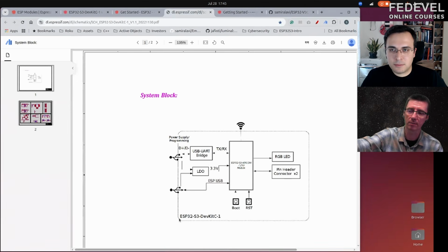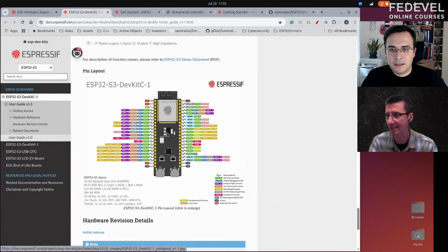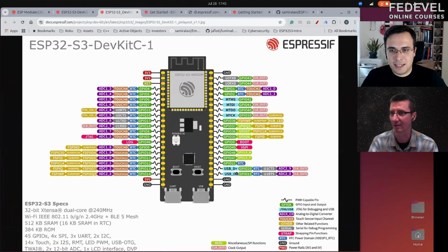This is nice. I use the picture a lot actually, especially for example, if I'm looking for pins which are supporting, I don't know, I2C. In this picture you can see very nicely which pins you can use or connect. Exactly, yes, this feature is quite useful. Usually when designing a product, this is what I do myself: I create an Excel sheet, I put all of the pins, and then during the design review, we decide on the functionality of each pin, and we make sure we don't lose pins or go out of pins.